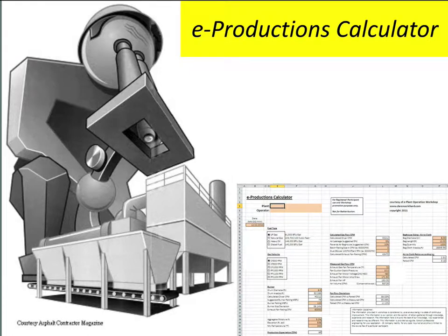Take some time to change the aggregate moistures, mix temperatures, and plant elevation, and you may be surprised how much these factors affect production. Changing the applicable entries on the energy calculator may also surprise you how much money you are leaving on the table and your contribution to greenhouse gases.